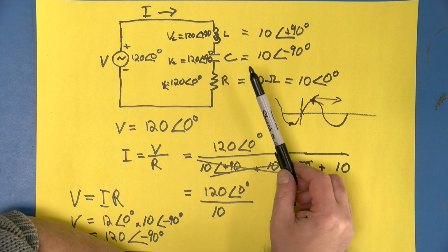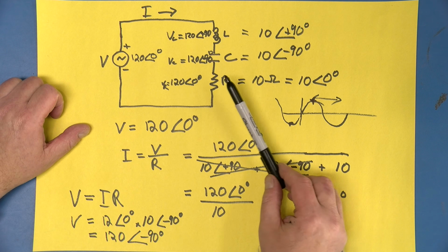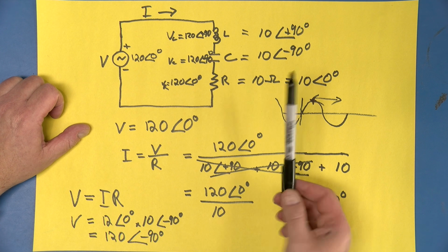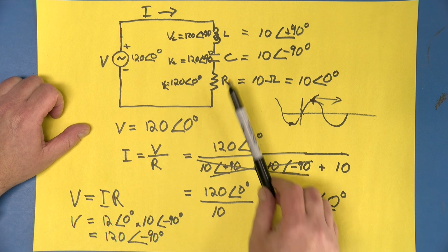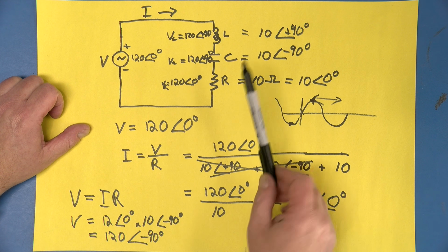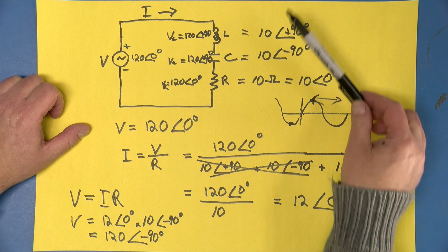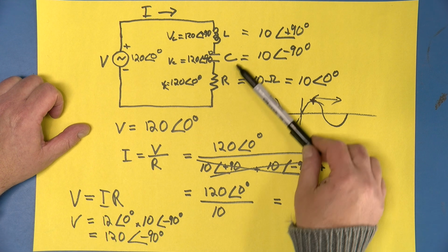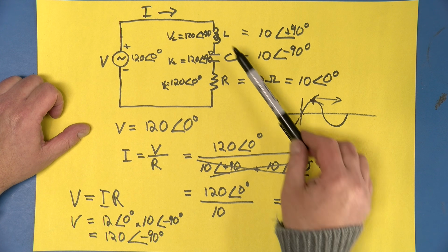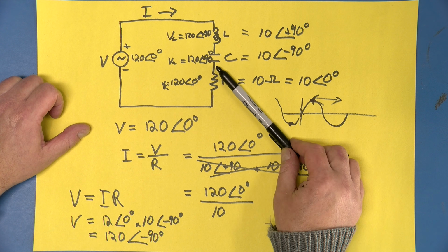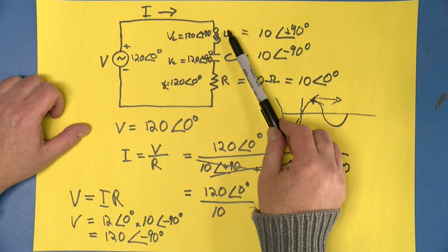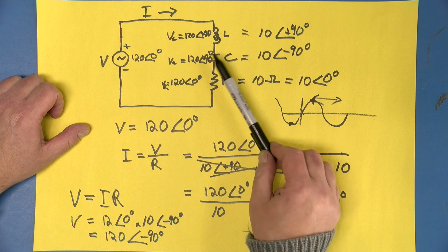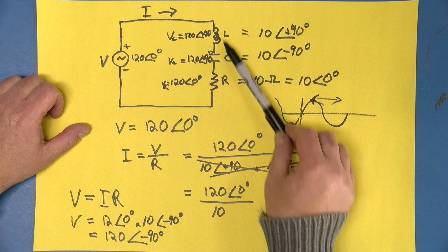Now that might seem very weird, but more than likely you've used circuits like this many thousands of times during the course of your lifetime. And they are what we call tuned circuits, because this situation where this impedance is equal and opposite to that impedance only occurs at one particular frequency. And by changing the size of the inductance or the size of the capacitance, we can change the frequency at which point they're equal and opposite.